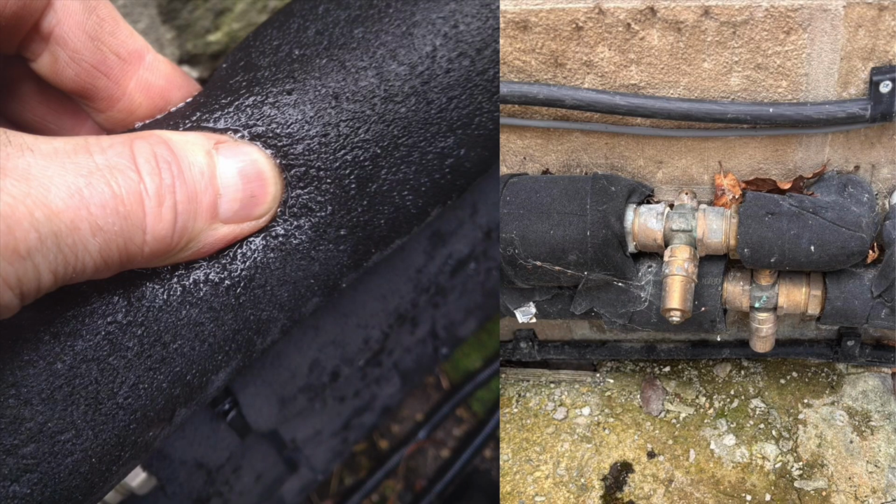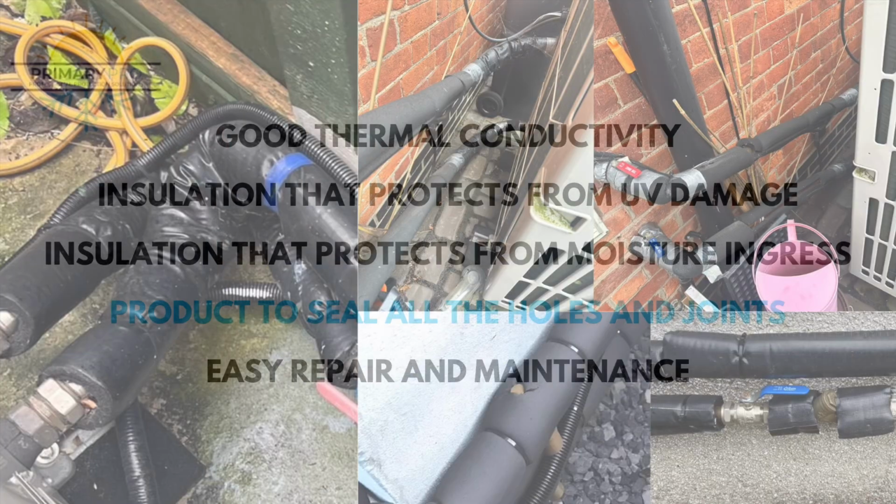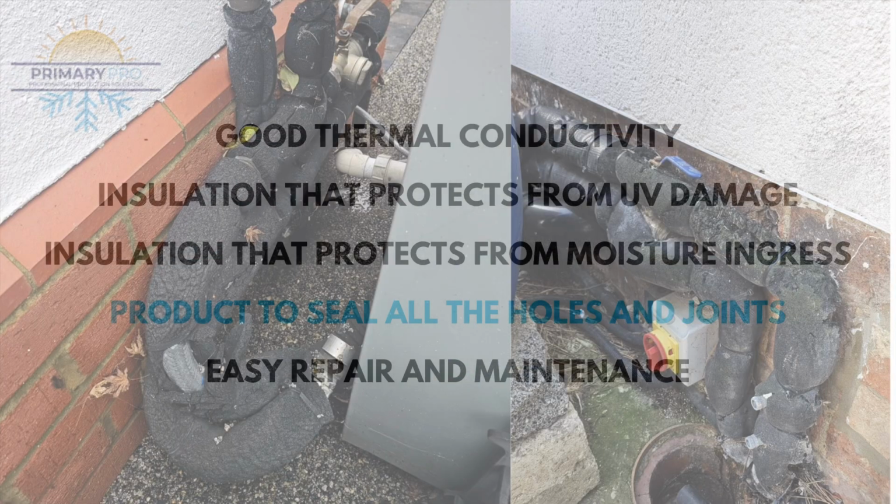and then starts to seriously affect the efficiency of the heat pump and system. So what we looked at is 5 main things after looking at all the problems and then trying to find solutions. We want good thermal conductivity, insulation that protects from UV damage, insulation that protects from moisture ingress, and a product to seal all the holes and joints, not just sealing the joints together, but to the heat pump, all the holes that you put through for the lever valves. They all need to be sealed to stop moisture and water getting in.